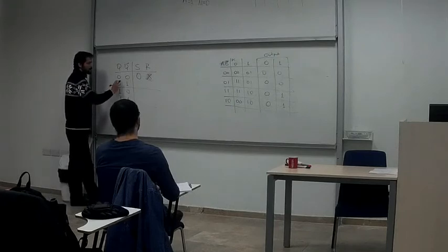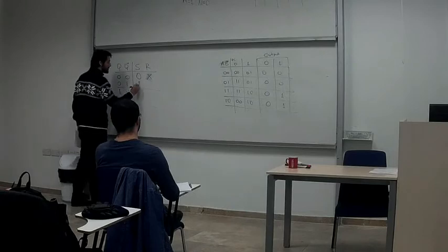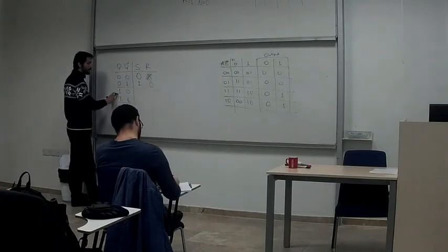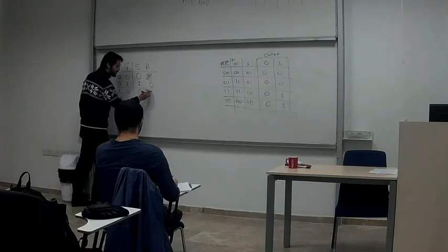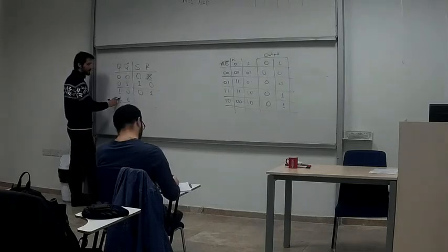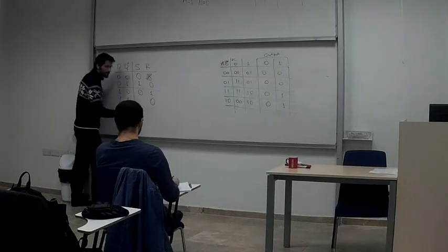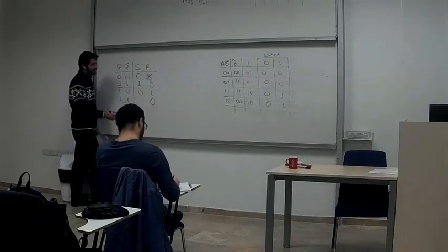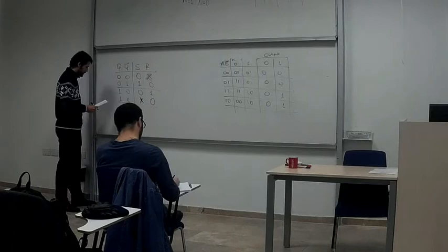My initial state was 0, then I had a 1. What is this? This is definitely a set. So it's 1, 0. I had 1, the next thing I know it's 0. This is definitely a reset. I had 1, and then I had 1 again. This is either retain state or a set. So in this case I have reset as 0 and set as X.